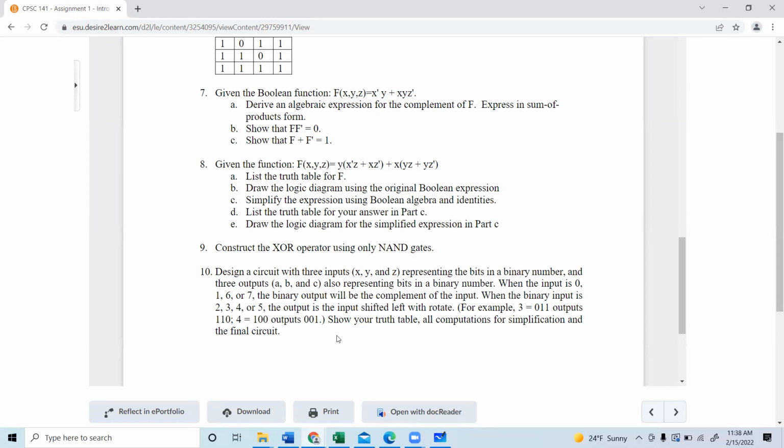This will be the statement given in the exam or the assignment. You make the truth table by reading this, then simplify the expression using Boolean identities or a Karnaugh map, give the final expression, and design the final circuit. Here I'm giving you the answer directly, A plus B C bar, but actually we don't know it, right? It is not given upfront for you.